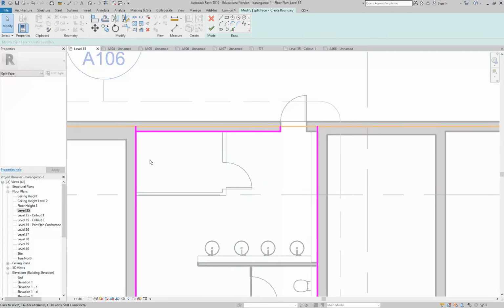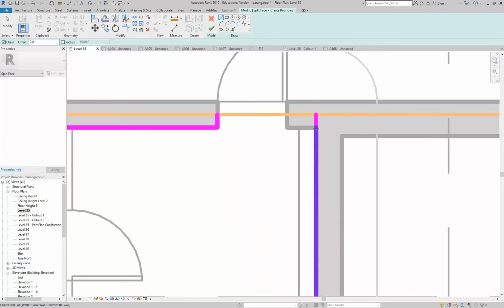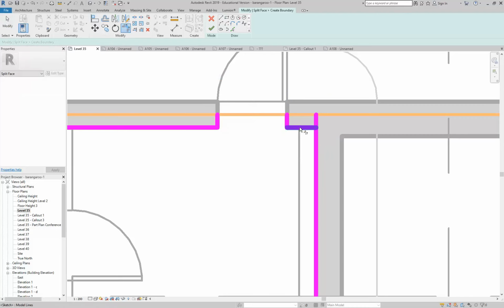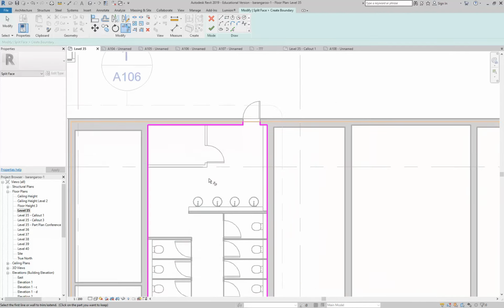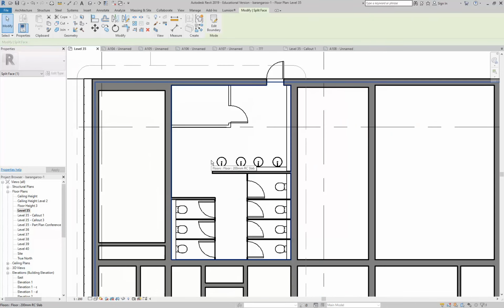Right, but there's no problem if the tiles go under the wall, really. No one will know except you, unless you want to get into quantities, and then you'd have to use a different approach anyway. So this works. But the method Carolyn mentioned is actually what I do, the stacking of floors, and I'll show you why I think that's a good option as well. But this works. So that way I've split the face, and now I need to have a tile material. So I'll just quickly make one.